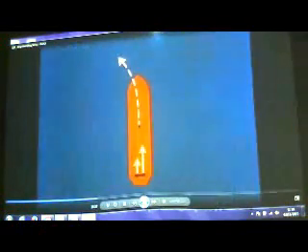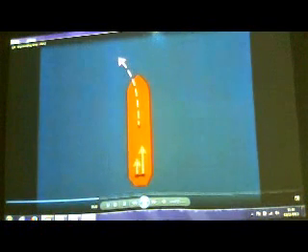Over the hull of this model, whose propeller has been frozen photographically, the water flow entering the propeller disc has an upward motion, shown by the tufts. The propeller's rotation causes the relative angle of incidence of the downgoing blade on the starboard side to be greater than that of the upgoing blade on the port side. The yellow arrows show the resulting imbalance of lift forces when the blades are near to horizontal, caused by the upward motion of the water. This will tend to turn the ship to port.